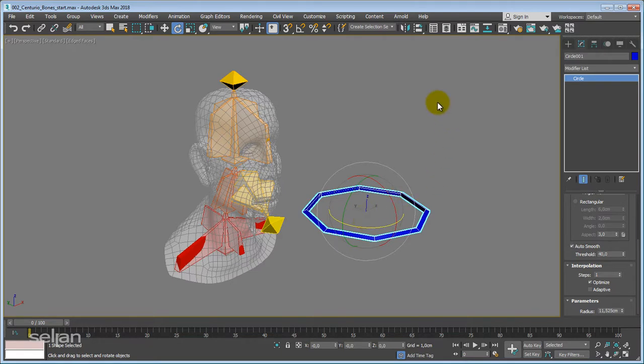Now here comes the trick. We have a line, but there are many ways to align something. I will use the top two aligns. The basic quick align hotkey is Shift A. I like Shift A. When I hit that with the model selected, my cursor changes, and I go over the shoulder because this circle will be aligned to the shoulder.